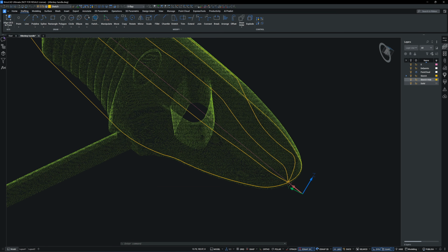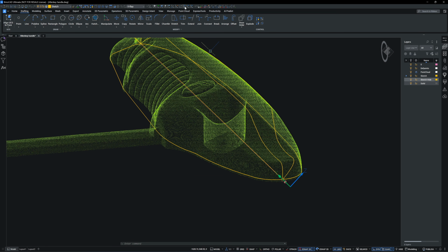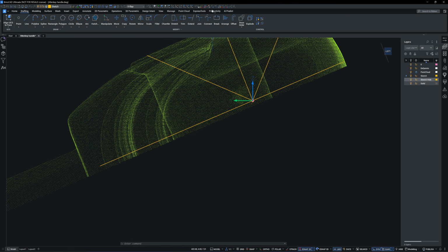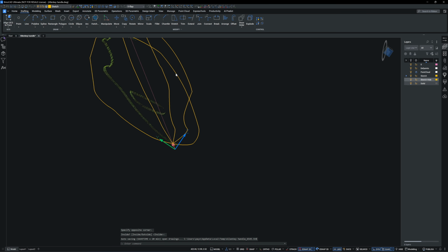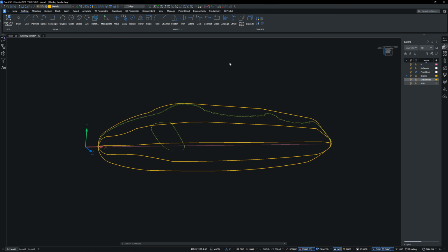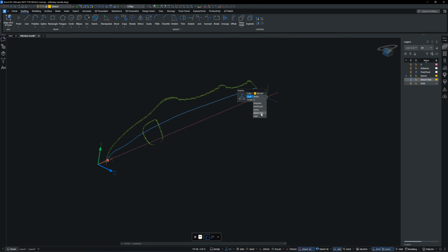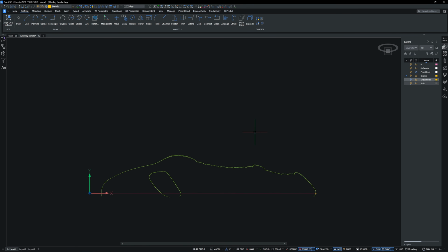There is still a large gap between the sketches, so I will add another by rotating the UCS x-axis 22.5 degrees, half of a quarter turn. The more 2D sketch frames you create, the greater the accuracy when defining the surface boundary.